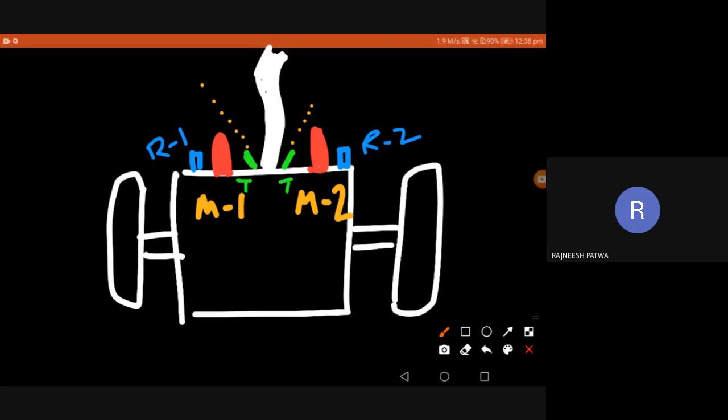Whenever I have a black surface, you should imagine that this is pointing towards the ground or the surface of the table where you're keeping the white line. Now, whenever my sensor experiences a white line, for example, white area coming to sensor 1, what is the meaning? My robot has tilted to the right, and my sensor may be over the white line.